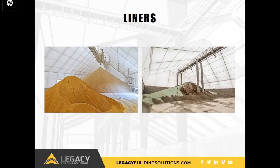Uninsulated buildings may also be lined for corrosion protection. Structural fabric, including Legacy's exclusive Exotech PVC fabric, is non-corrosive. Adding a fabric liner to the underside of the frame keeps the steel frame out of contact with all corrosive elements, including salt, fertilizer, and moisture. This is a cost-effective alternative to epoxy paints that are often used to stop corrosion, and a permanent alternative that is not subject to pitting or thinning when exposed to corrosive elements.